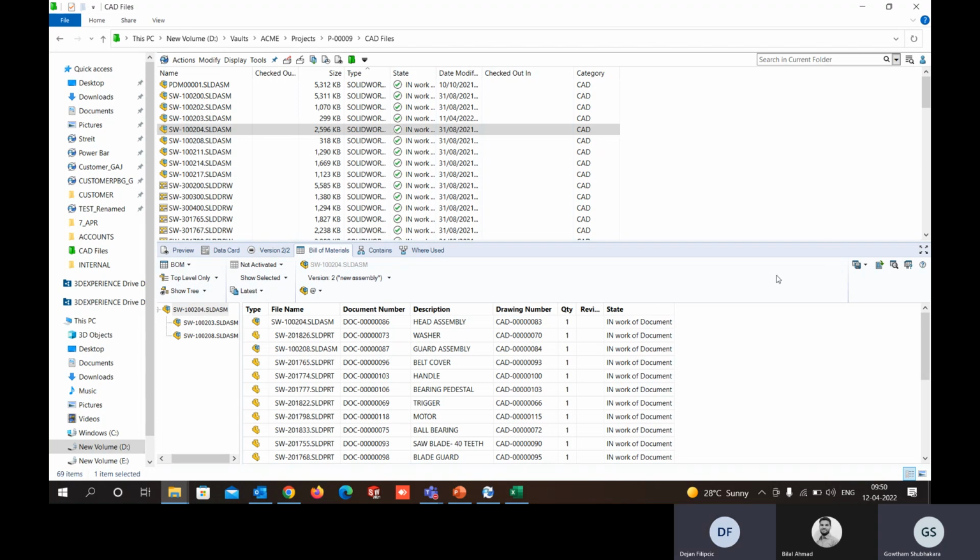The question is, when you save it, does it change dynamically or does it become stationary? Actually, whenever you save this particular bill of materials, it will be saved as a named bill of materials, and it will be one single file. When you make another modification, the existing file will not be modified. It will be the same.